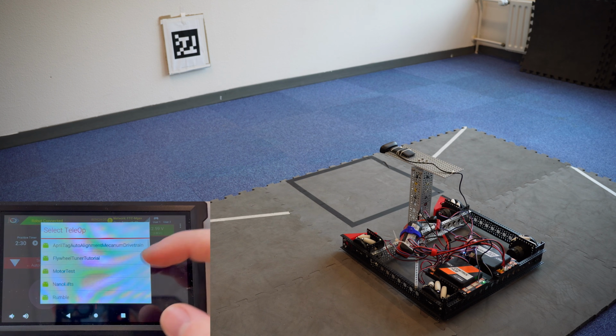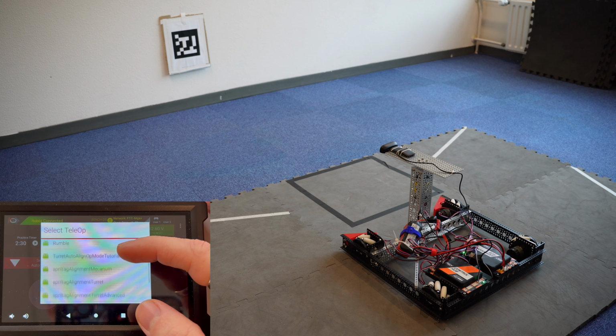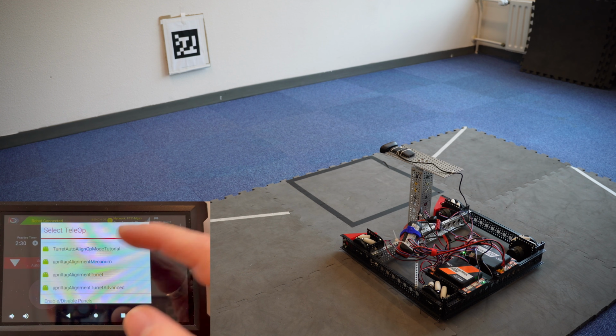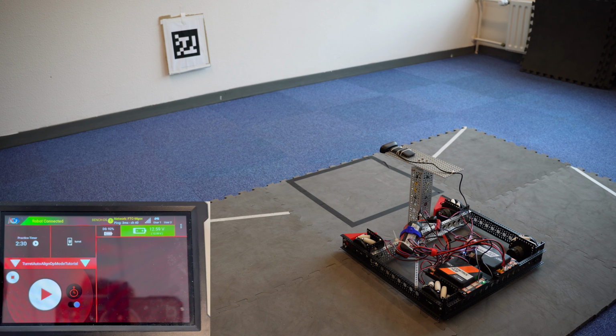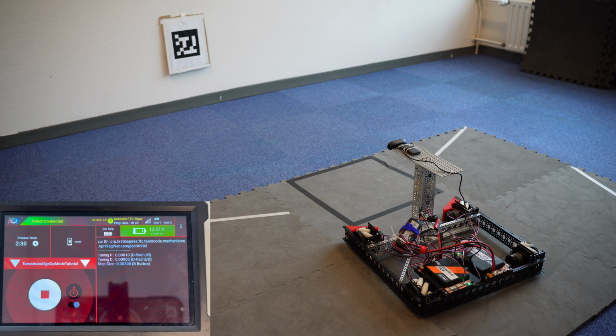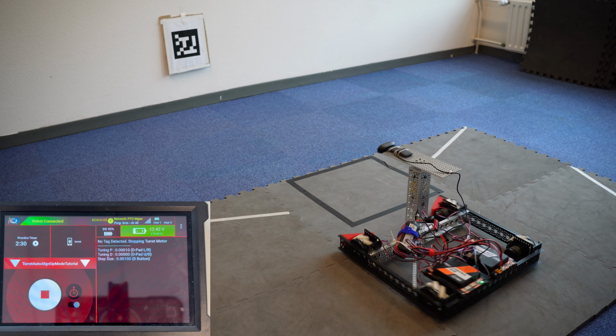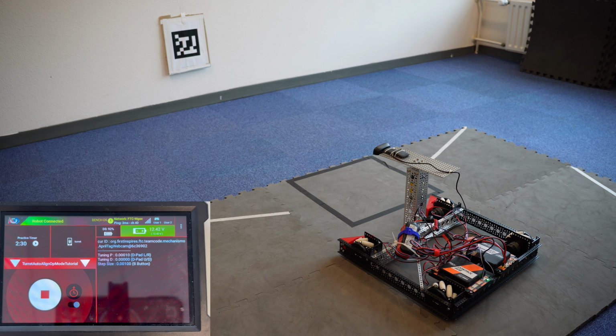So let's go ahead and set up, I believe this is the turret auto align auto. We'll initialize this, and then boot it up. Now looking at this, I should be able to rotate my robot to the right, and we should have this start auto aligning. It looks to me that it's presently not auto aligning, because we can hear that coil whine. What that tells me is that if it's not auto aligning, our P is a little bit too low.